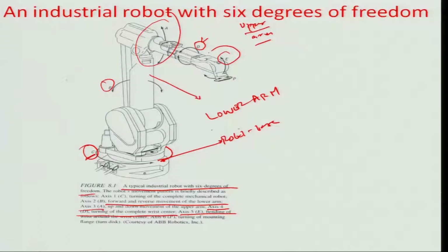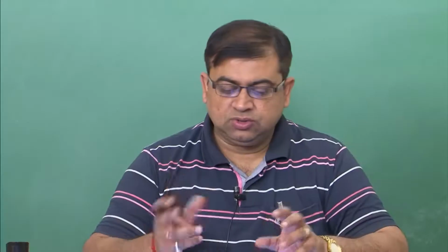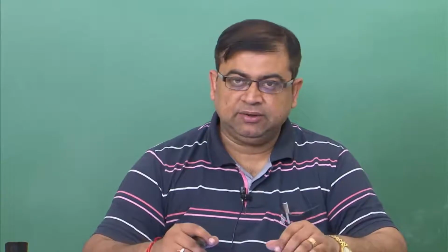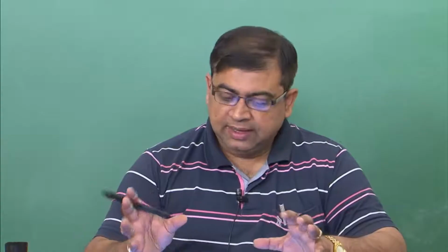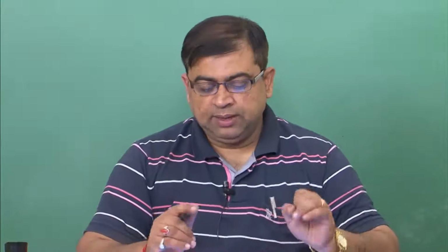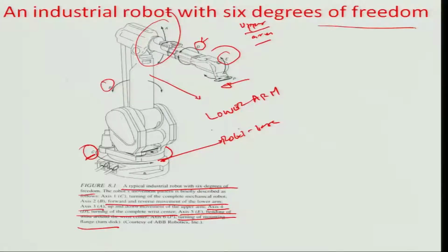And then finally, the 6th axis of the robot is by virtue of the turning of the mounting flange or the turn disc, which would do some operation. Maybe let us say we are talking about dispensing of spray paint, where there is a flange rotation which is very important to atomize the paint in the automotive industry, or then we are talking about some kind of a painting, polish or buffing kind of a robotic system, where again such rotations are used for moving the buffing wheel very close to the body. So, that can be accumulated with all these 6 different motions as in a human arm, and this is typically how a robotic system is classified geometrically.